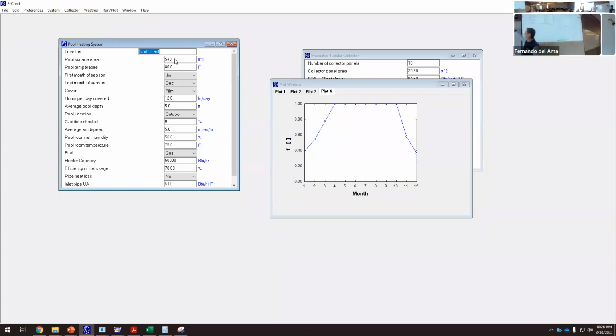So all the energy that we are gaining here, we don't need that energy because we don't have a heating system. But if we don't move this water, the system will suffer this overheating and it will burst. Okay, so we need to take this energy to an energy sink. So where I can release energy there and nothing happens because here we have a huge mass of water. But we are losing energy. This is 70 Fahrenheit. And the outdoor temperature over the night is 60 Fahrenheit. We are losing heat.